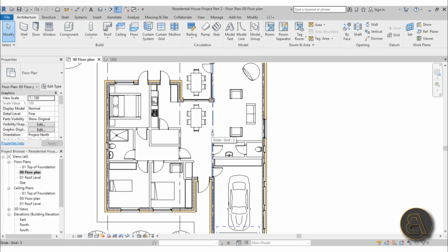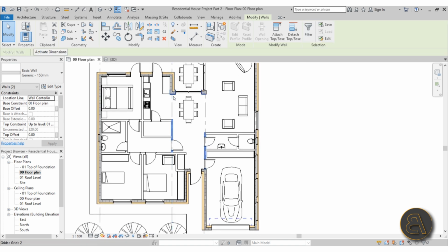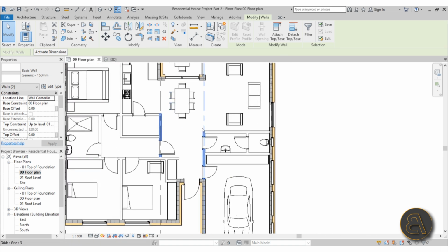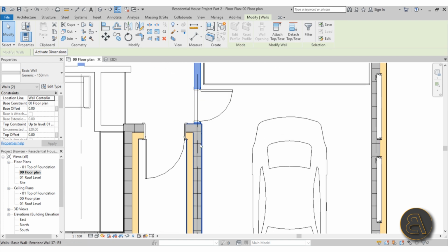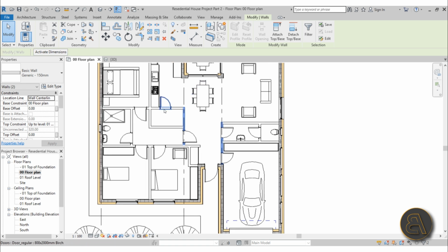Now for the interior walls, we're actually going to have two types of interior walls. We're going to have a bearing interior wall as well as the regular separation interior wall. So the bearing walls are this one and this one over here. As you can notice, they're running alongside these grid lines, so you have to actually make them a bit thicker. They have to match the structural layer of this wall, but for the rest we can use just brick and some gypsum wallboard for the exterior.